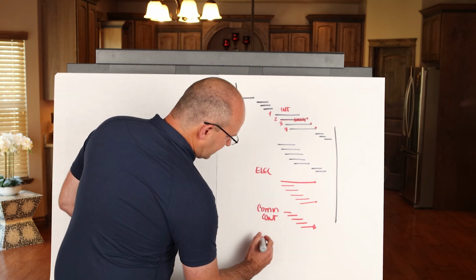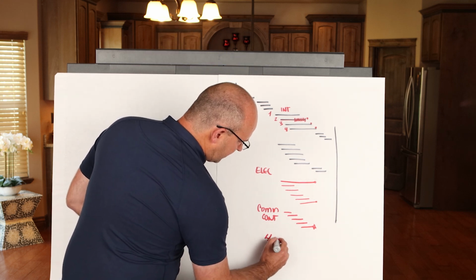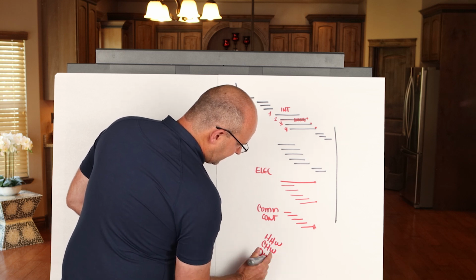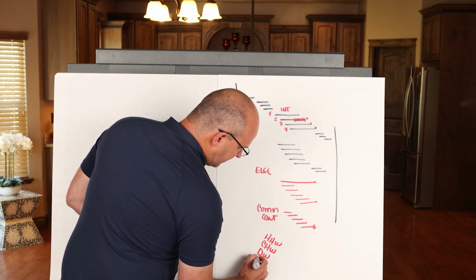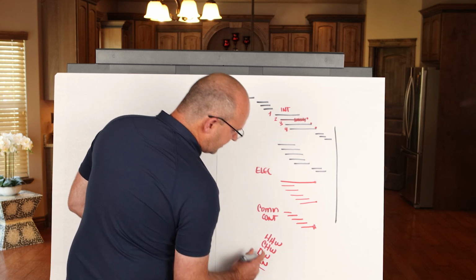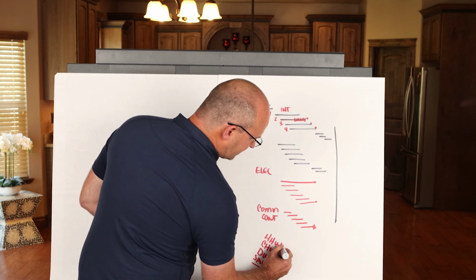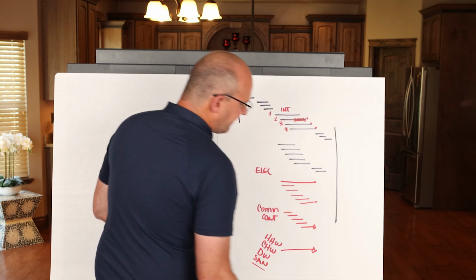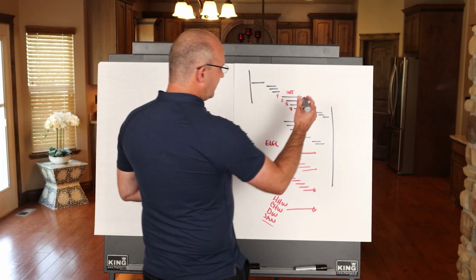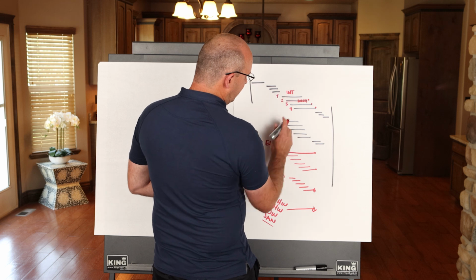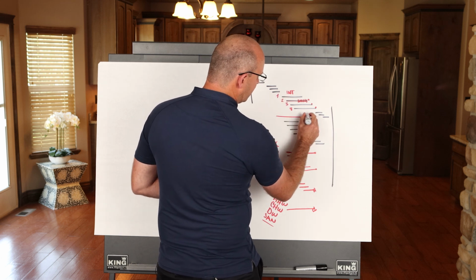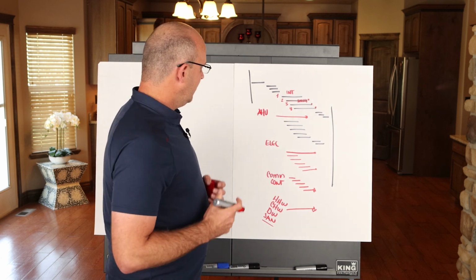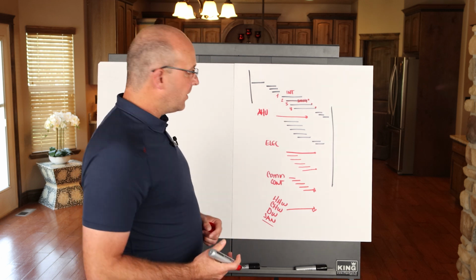The other thing is I want to make sure that heating hot water, chilled water, domestic water, and I think probably you're going to need your sanitary so that you can drain some of this stuff. But I need to make sure that all of the hydronic piping systems are 100% complete. Now, the only other thing that I would say is wherever you put it here in the overall production plan, I want to see when do you land your air handlers and your equipment and your exhaust fans, and when do you land your pumps.